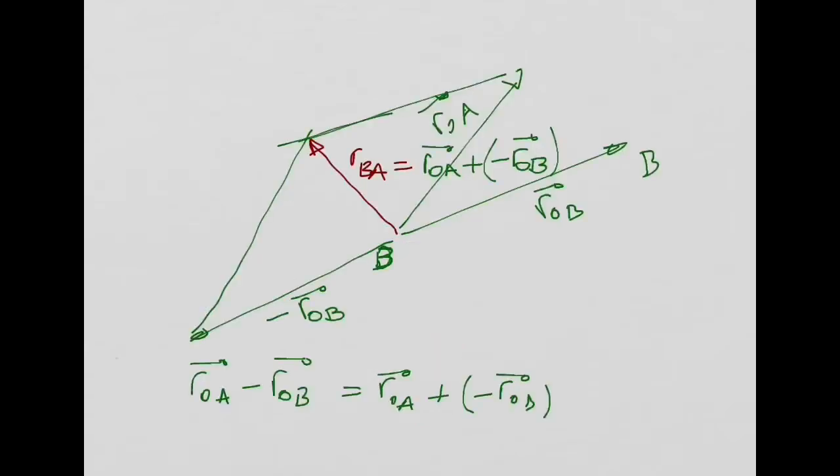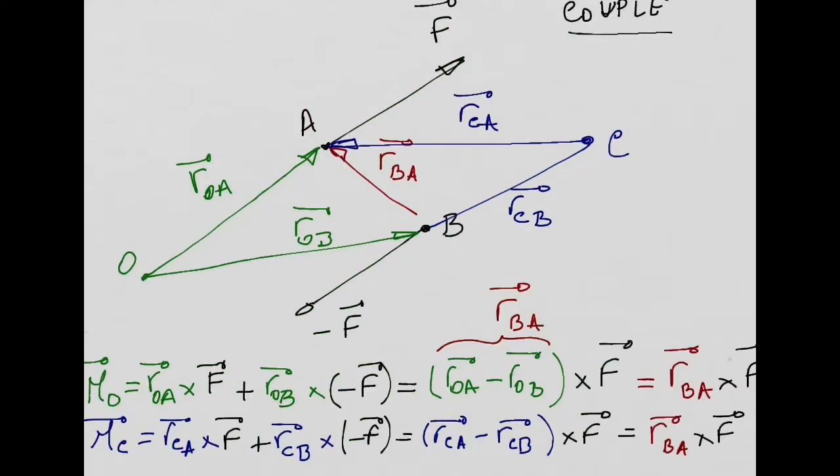Isn't the moment supposed to be anti-clockwise or clockwise? There is a convention for the moments. I use the one that says if your moment rotates anti-clockwise, I assume positive moments. If they rotate clockwise, it is negative moments. Right? But we will see many examples, all right? Don't worry about that.